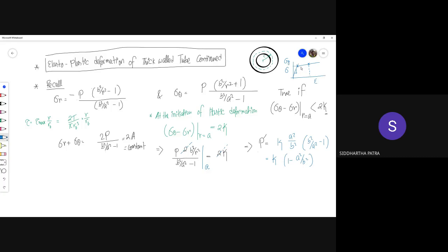So the elastic equations are valid, and so are the plastic equations. Okay, and actually that's how we got the expression for p prime. So this is the plastic part of the equation, and these two are coming from elasticity. And both of these conditions are valid at yielding, and only at yielding. At any arbitrary amount of plastic strain, that would not be valid. Although the material is still going through plastic deformation, that expression is not going to be valid.